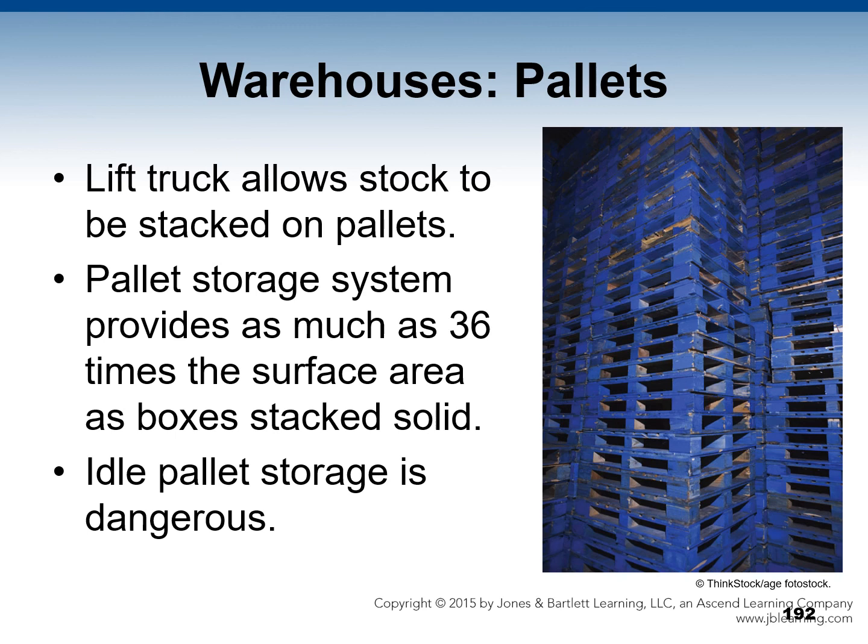Idle pallet storage, or pallets without the product, such as you see here in this picture, is a dangerous practice inside of buildings. There are too many examples to even refer you to one, but if you go back through Los Angeles County in the last 5 years, I guarantee you're going to find several pallet fires. Pallet fires can occur outside or inside. If you just go by warehouses, sometimes you'll see pallets stacked outside like this, but sometimes they're stacked inside. It's a dangerous practice, and pallet fires happen all the time, but the practice goes on, so you need to be aware of it.